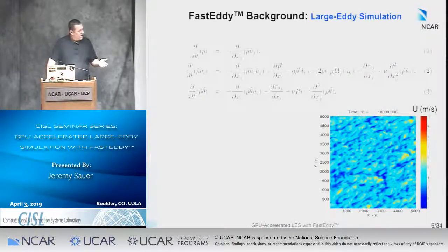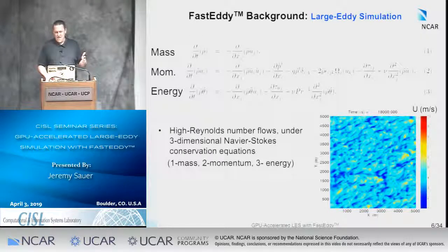So what is Large-Eddy simulation? It's these specific equations. I had to throw some equations into the talk. It's really about high Reynolds number flows under three-dimensional Navier-Stokes conservation equations, the first being for mass, second for momentum, and the third for energy.